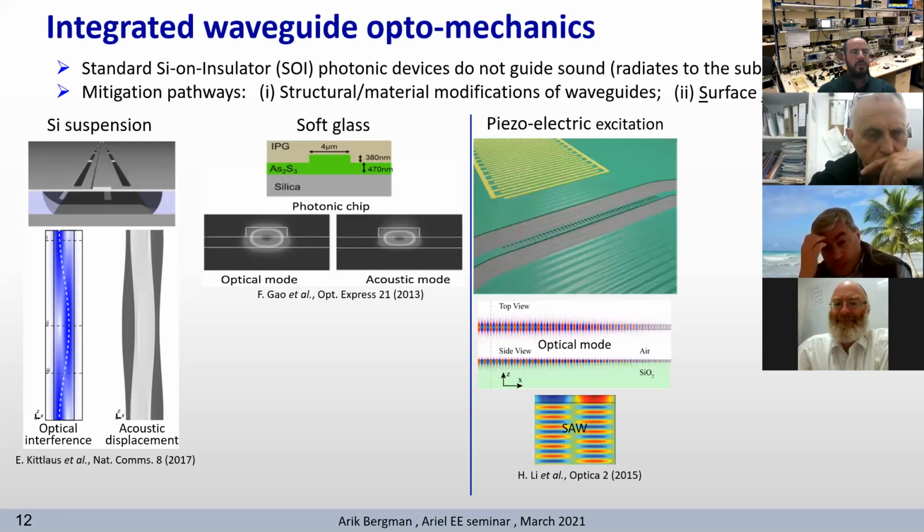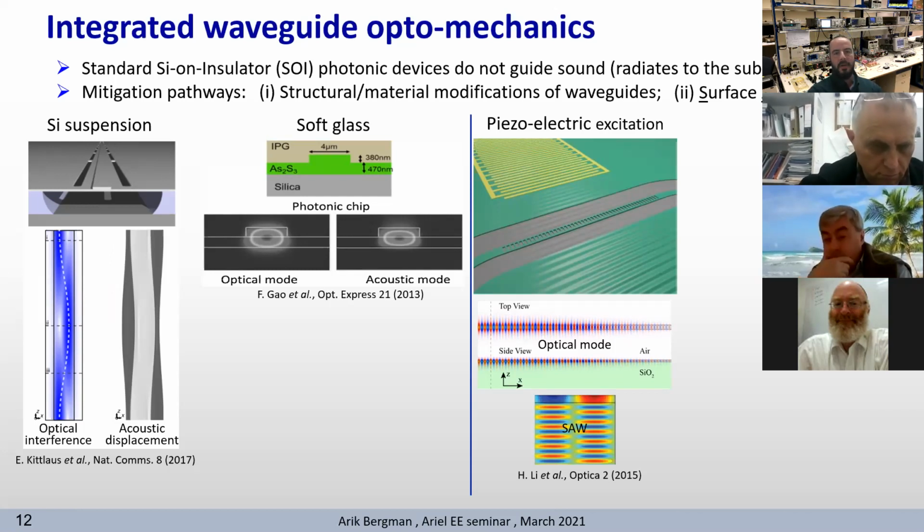The second approach is the introduction of surface acoustic waves into photonic circuits. The most standard techniques rely on electrical excitation of surface waves in optical grade piezoelectrics. These material platforms have very large electromechanical transduction efficiency and also support optical waveguiding. Lastly, as a consequence of the optomechanical coupling that is designed to take place in the waveguide core, the radio frequency information is imprinted on the optical carrier.